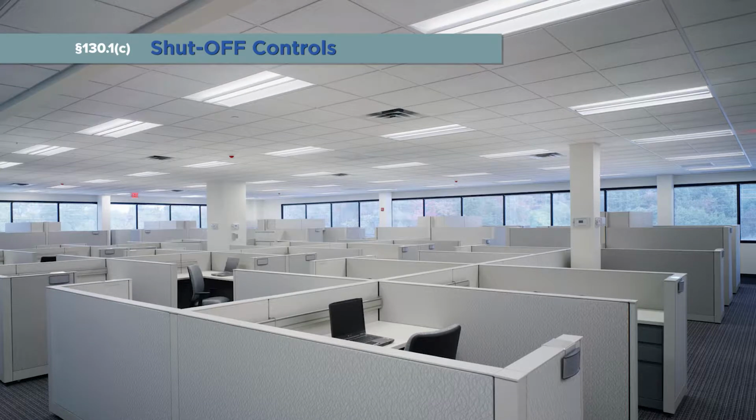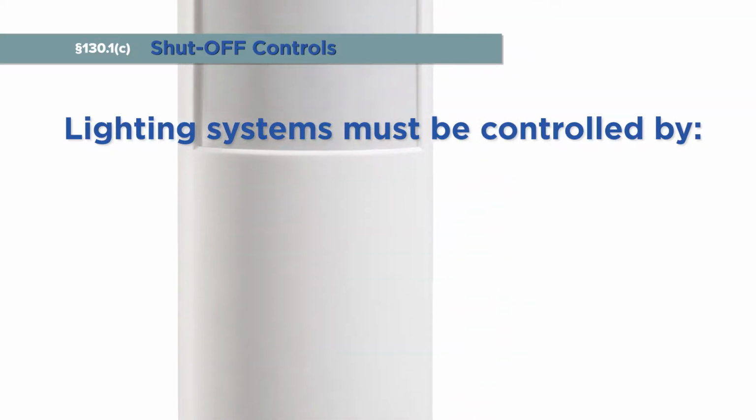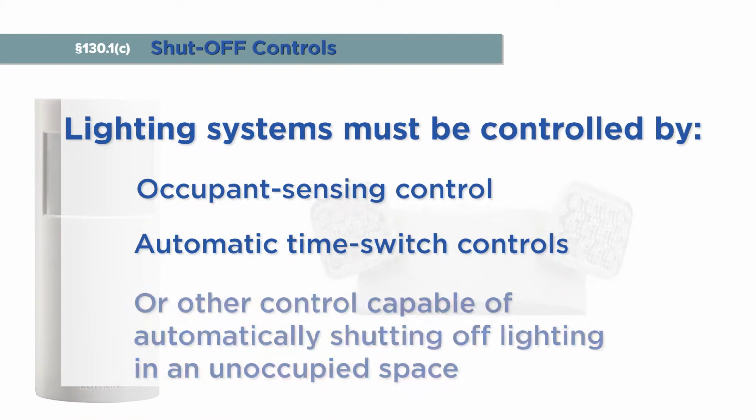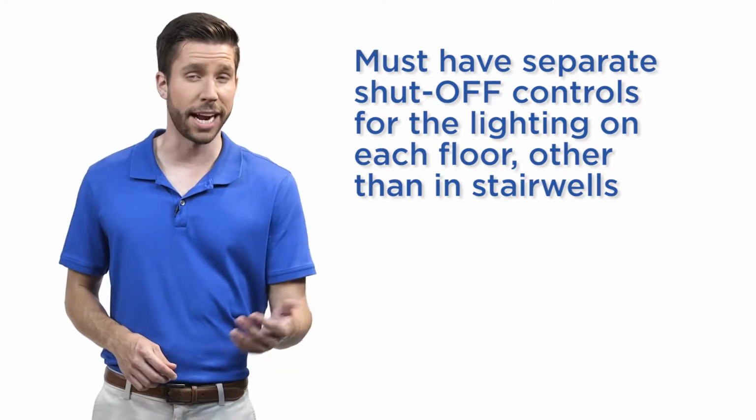In addition to area controls and multi-level lighting controls, which we learned about in Modules 2 and 3 of this video series, all installed indoor lighting must be equipped with shutoff controls that meet the following requirements. The lighting system must be controlled by an occupant sensing control, automatic time switch control, or other control capable of automatically shutting off all of the lighting when the space is typically unoccupied. Additionally, there must be separate shutoff controls for the lighting on each floor, other than lighting in stairwells.